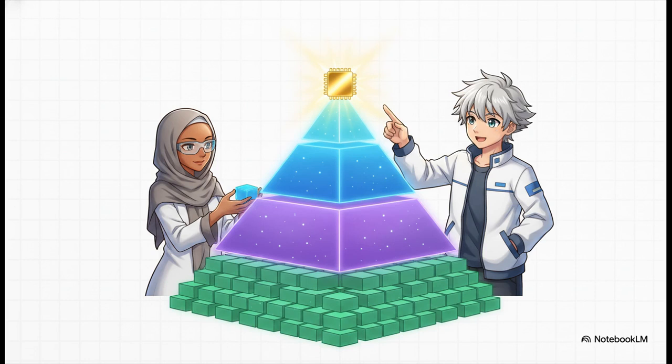So, what's the actual fix? The crucial point here is that the solution is never just one perfect component. The real solution is a memory hierarchy. Instead of relying on a single chip, we organize memory devices into a very structured hierarchy. We combine smaller, very expensive lightning-fast memories right next to the processor, and we supplement them with larger, cheaper, and slower memories further away. The whole goal is to bring frequently used instructions as close to the processor as humanly possible. Let's start right at the very top of this hierarchy.